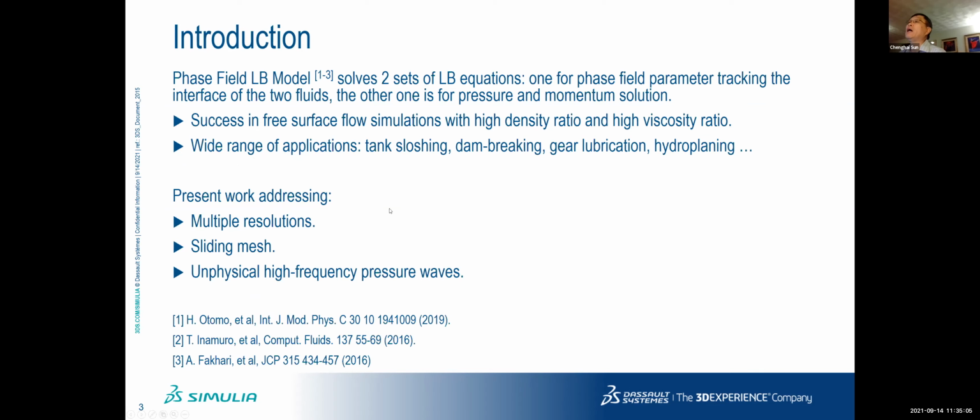The phase field model solves two sets of lattice Boltzmann equations. One is for the phase field parameter that tracks the interface of two fluids. The other one is for the pressure and velocity. Phase field has been very successful in free surface flow simulations, which can handle high density ratio and higher viscosity ratio.